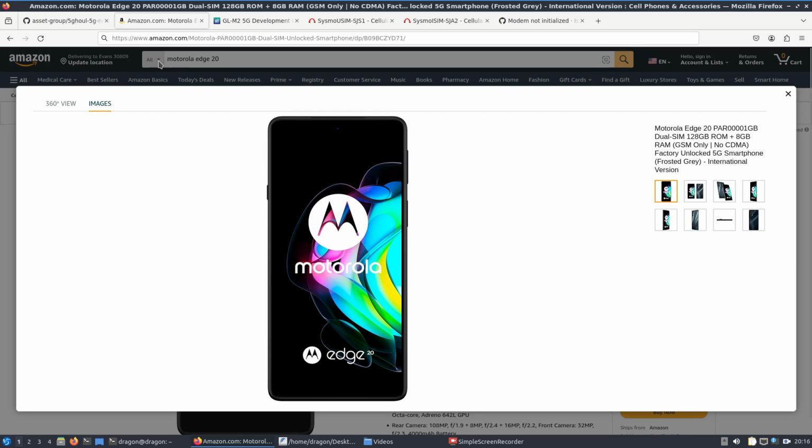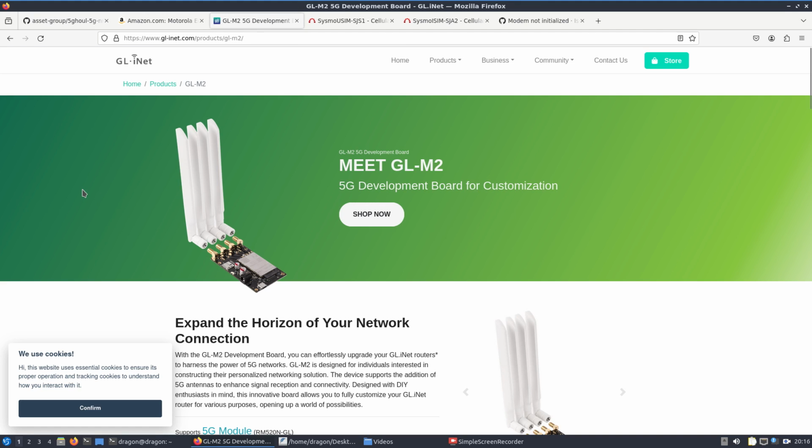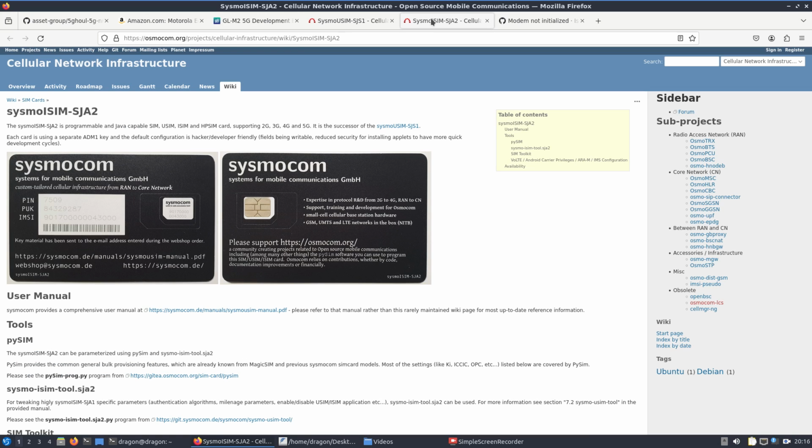So I moved from that over to a 5G development board, and this particular one had a Qualcomm modem, and I initially picked up some additional Sysmocom SIMs, and there's probably nothing wrong with these. There's probably just some programming that I need to do, but these SIM cards had an MCC MNC of 99970, which was different than the older ones, which was 90170.